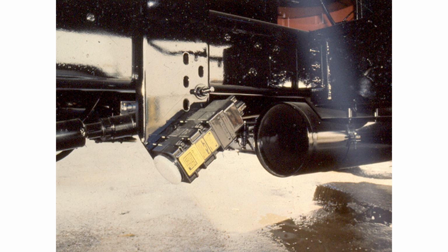We take sensors with the radar, okay? We're counting our speed with the radar. When we talk a little bit about maintenance of the equipment, the radar is a crucial part of the machine. If I don't get a good ground signal, it's not counting how fast I'm going, then I'm not going to get the right application rate. So you want to keep this lens clean, you want to keep that serviced well, you want to make sure your radar is in good working order.